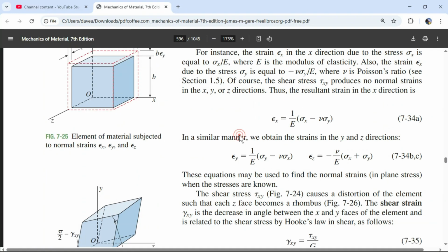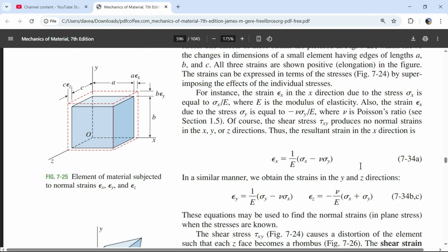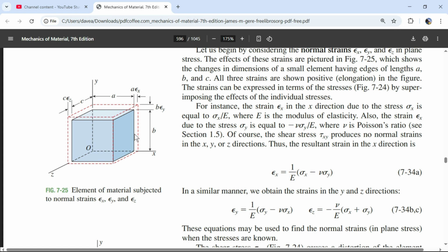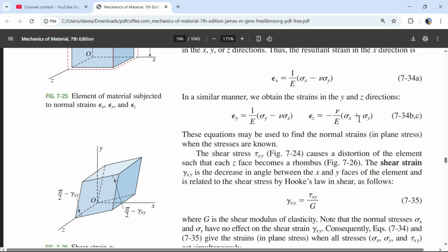but hell yeah. So we were talking about how the strain in the Z is just due to the normal stresses in the X and Y, and how, if they're positive, they're going to suck this face in due to Poisson's ratio. And so that happens with that normal stress times Poisson's ratio divided by E, and that's going to be the strain. So yeah, because this would be the resulting stress on the Z face.